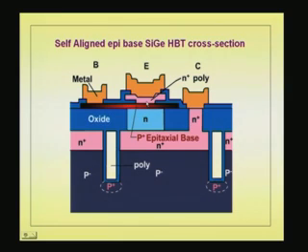Okay. This is another thing which is very attractive for self-aligned techniques, and also you put N plus contact, it is slightly diffused into this region, and makes a single crystal very shallow N plus junction or N type junction, and then a contact is taken onto this N plus layer. Okay. So, this is the structure here, and of course, you have these techniques people use in silicon technology for trench isolation, etc., where you put a trench, oxidize it, put polysilicon. Okay. All those techniques are there for isolating devices and integrated circuits. This is the approach that IBM has been using, and the device structures are micron.